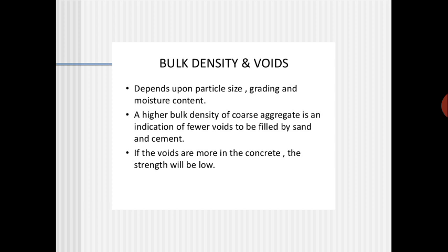A higher bulk density of the quartz aggregate is an indication of fewer voids to be filled by the sand and cement. Means if high bulk density is there, it means fewer voids. Then if fewer voids are there, of course those fewer voids should be filled by the sand and cement. That proportion should not be like what